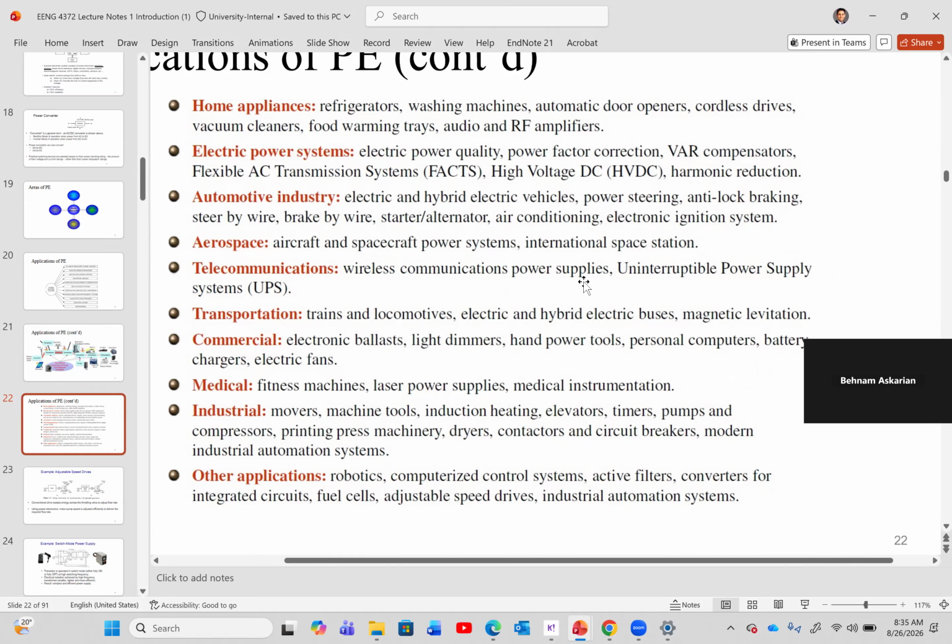And they have become very popular since the rise of hybrid vehicles, when the Prius came out. The problem with those hybrid vehicles is that most of the time when you're in traffic, the motor turns off. So when the main combustion engine turns off, they had a problem. The problem in the design was that when you lose the engine, you lose the belts. So you're going to use power steering, you're going to use the brake booster, because these brakes usually have gas boosters, which are connected to the exhaust and help you boost. I don't know if you've worked on cars, the brake boosters. So it helps you to brake.